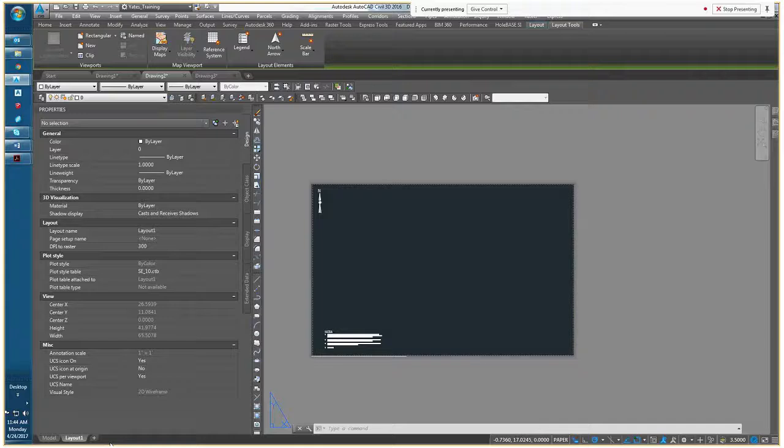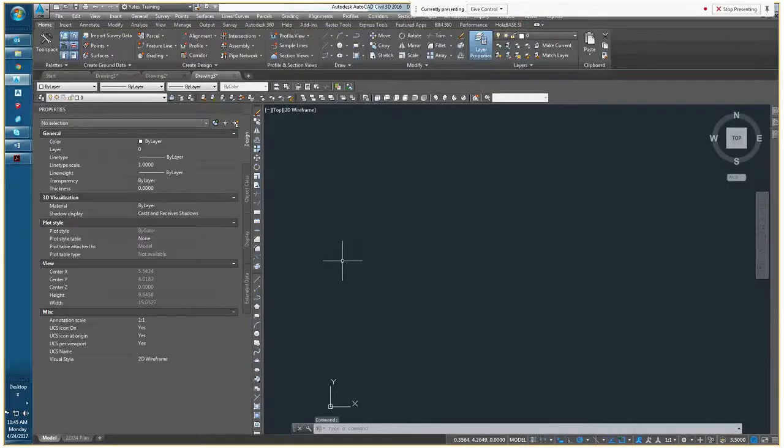But for all other drawings, this will include most of your XREFs, your title block drawings, your cover page, your legend sheet, almost any other type of drawing, and a lot of your detailed drawings, are just not going to need to start in the Civil 3D template. You don't need that huge bloated layer list, you don't need all the styles, and you want to just start with your detailed DWG if you're doing just a plain Jane set of 2D line work for your project.